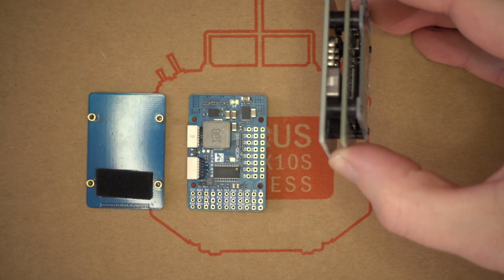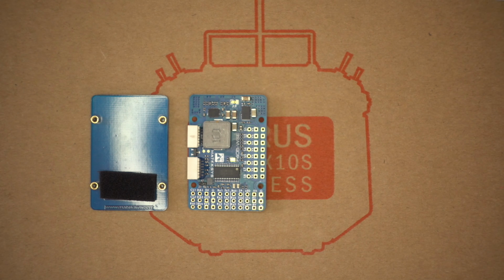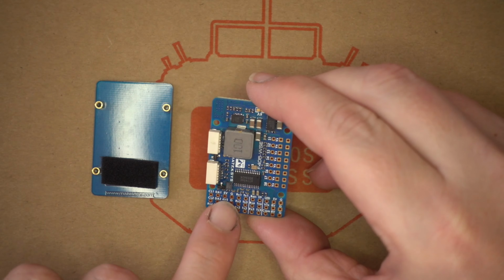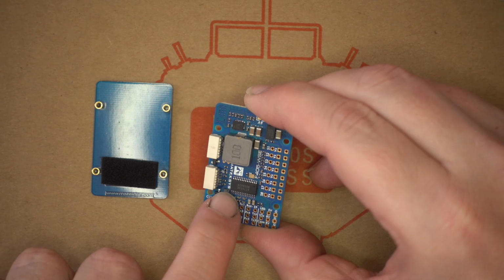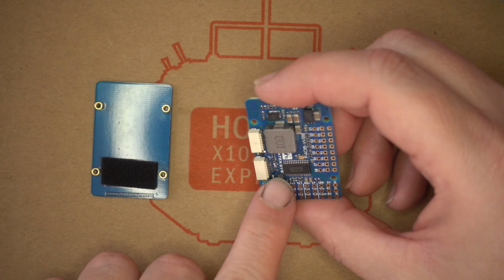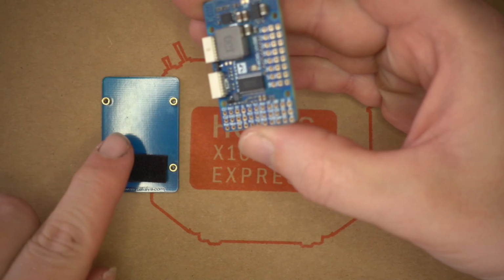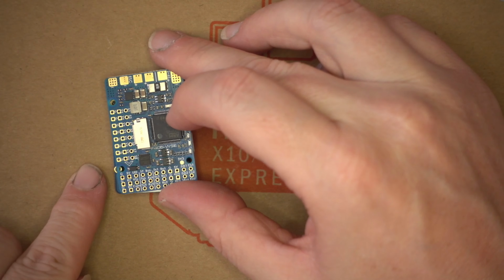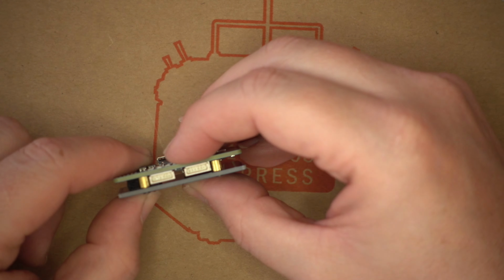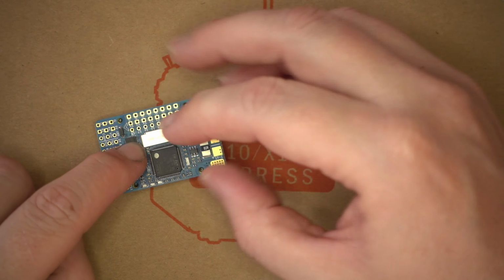Now, I didn't know I was going to take the bottom off of this, so I thought I'd show you it now. What this foam is for is covering over the barometer just so that it gives more consistent readings. The barometer is this little chip here. You can see it's got a tiny hole in it. Sometimes they're silver in color, but you can usually tell them because they've got a tiny little hole just to let the air in. When you're putting this together, you want to make sure that the barometer is over the foam. The foam is a little bit taller than the standoff, so that it just gives a nice squish when it fits together. So make sure that your foam is in the right place for the barometer before you screw this together.